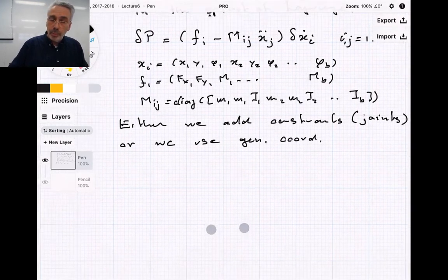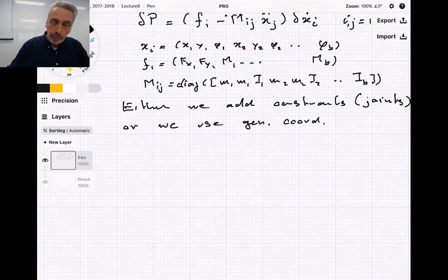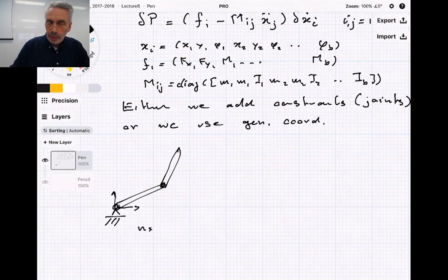And as an example, if you take that double pendulum, one pendulum here, and then connected is the other one, two hinges, we have a support. Of course, we have in total n is 6. We have, because we have two bodies, x and y, but that's not so important. Center of mass you can indicate here. And by counting, we come to the conclusion with the 4 constraints that m is 4.